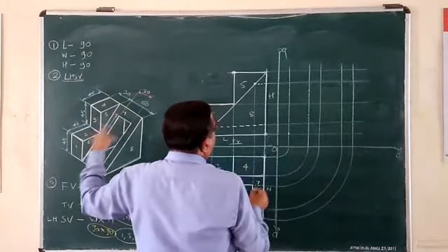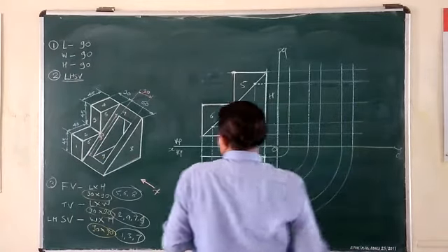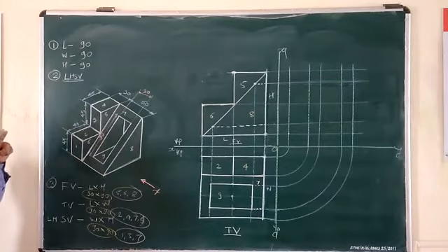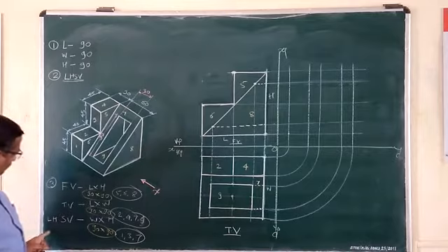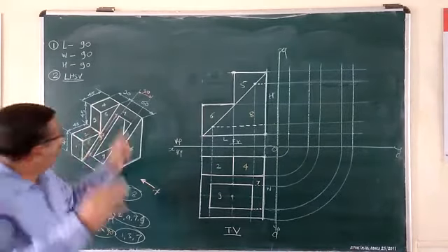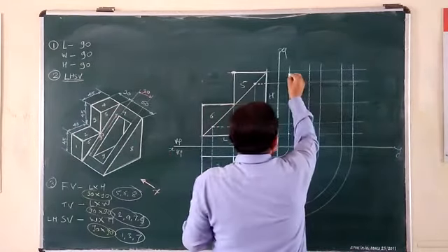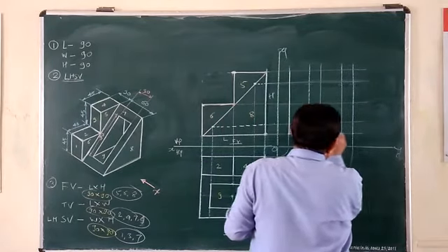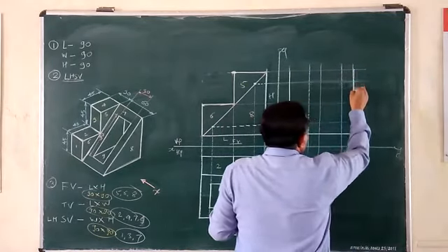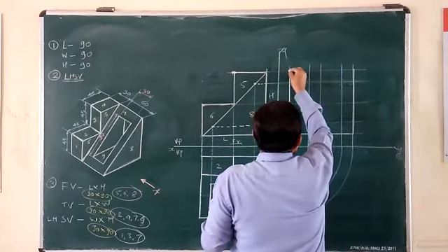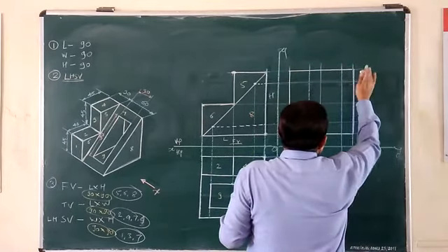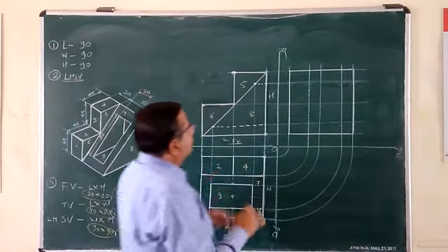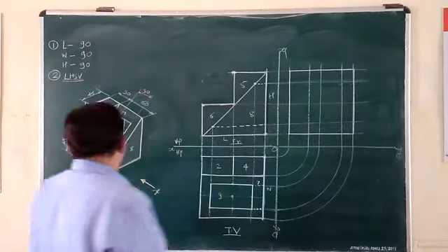So this 90 by 90 outline, first of all, when you observe in this way, at a glance what will appear is only a square of 90 by 90. We noted down here, LHS is 90 by 90. So the entire outline will be visible outline. It should be shown by a continuous thick line, because at a glance, before observing keenly, only a square will appear in that direction. Now the inner parts we are going to show.